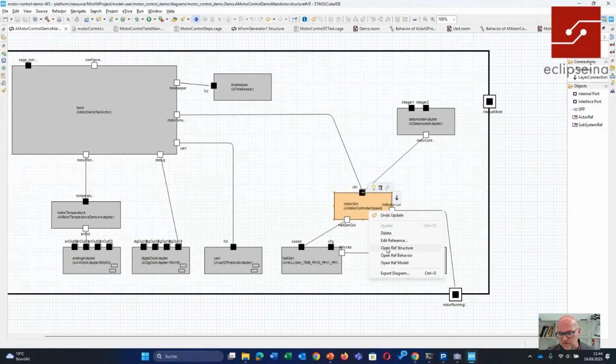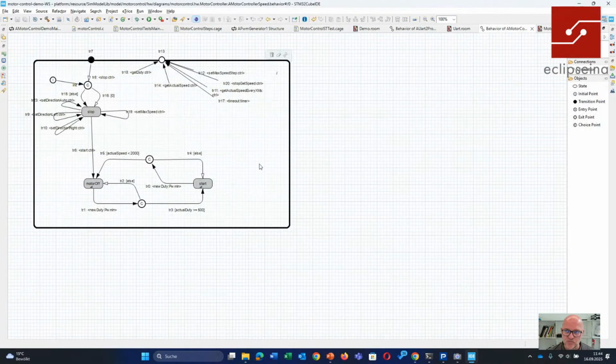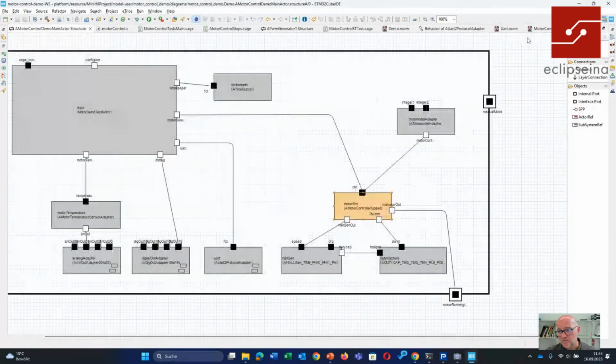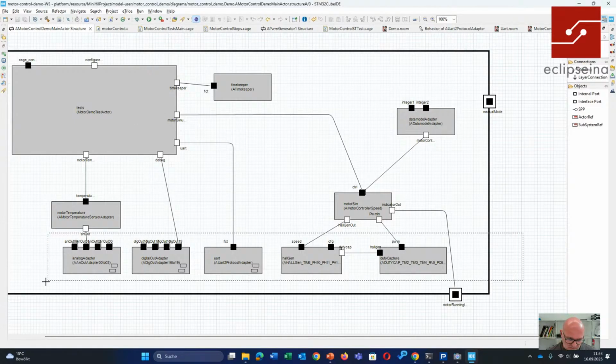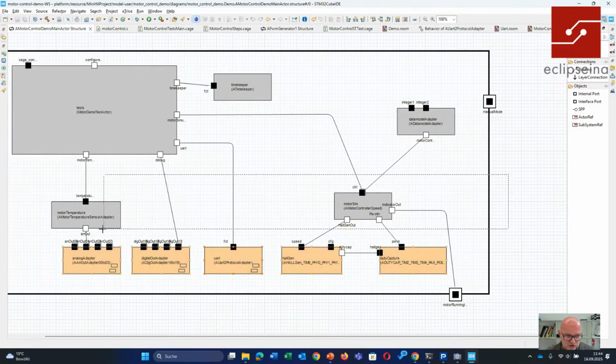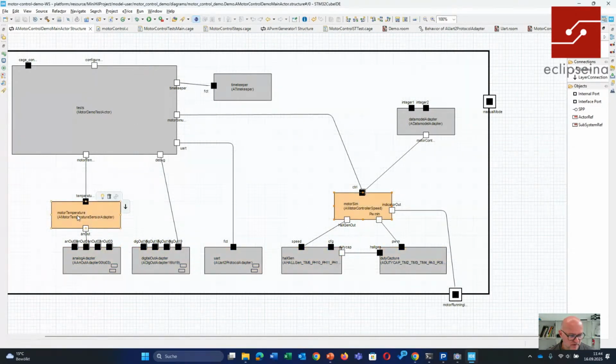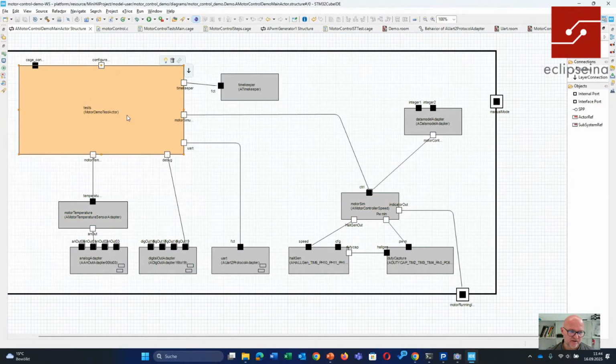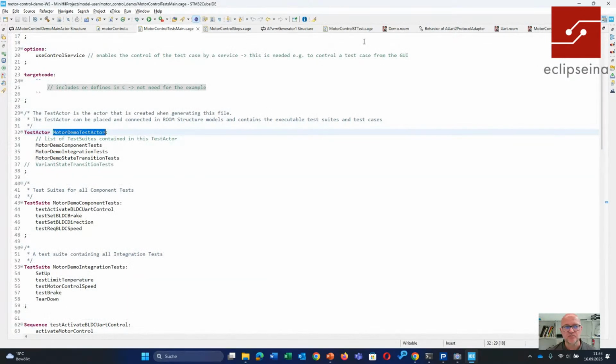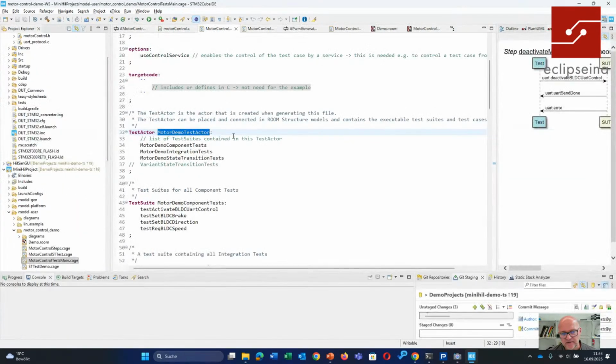Here we have a motor simulation. In this case, that's a state machine. You could also integrate a MATLAB Simulink block to simulate your environment here. So IOs, simulation environment, motor temperature, motor simulation, closed loop, open loop. And here I have my test cases. And instead of a state machine, I describe my test cases in a specialized language, a test language.